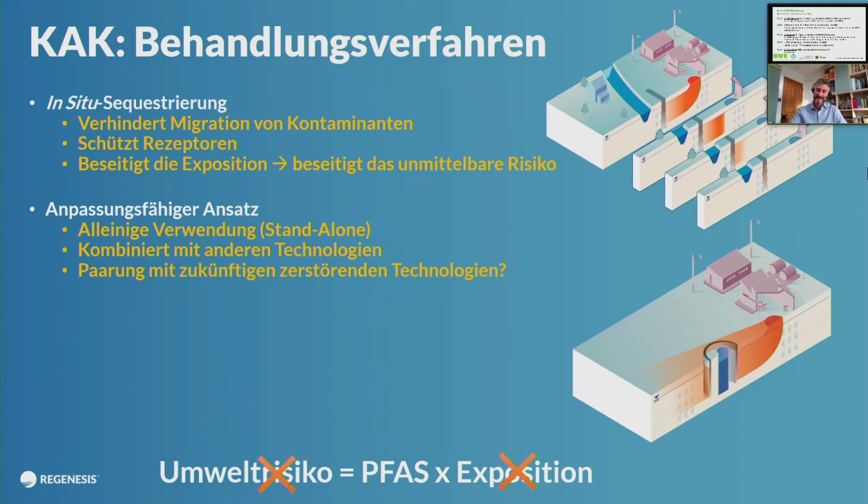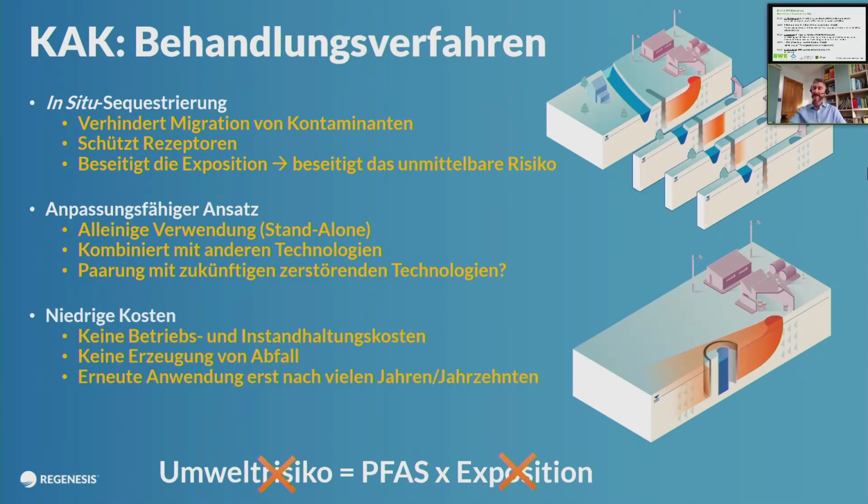I think as things develop, just like every other contaminant that we come across, generally on a site, multiple technologies are used. So I can see more and more that this technology will be used in conjunction with source treatment, and that might be stabilization, it might be excavation, it might be pump and treat with additives, etc. It might also be linked to destructive technologies as they develop.